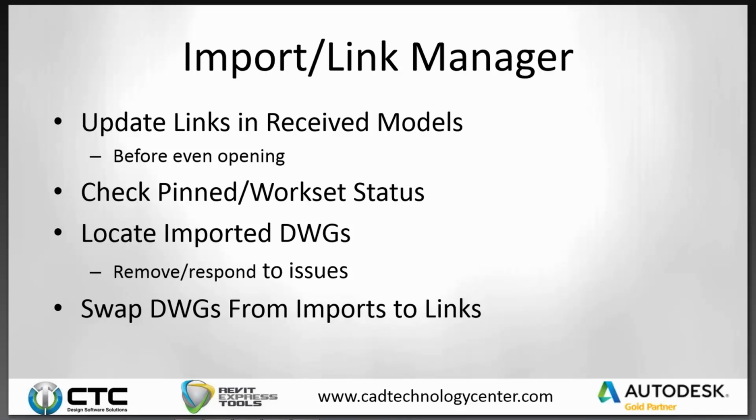Also, and this is an incredibly important step, and this is one of those things, we're talking project cleanup, that can go awry in people's projects. I've seen this happen a lot lately where users, instead of linking models, or maybe they linked them originally, have imported DWG files into the actual production model.